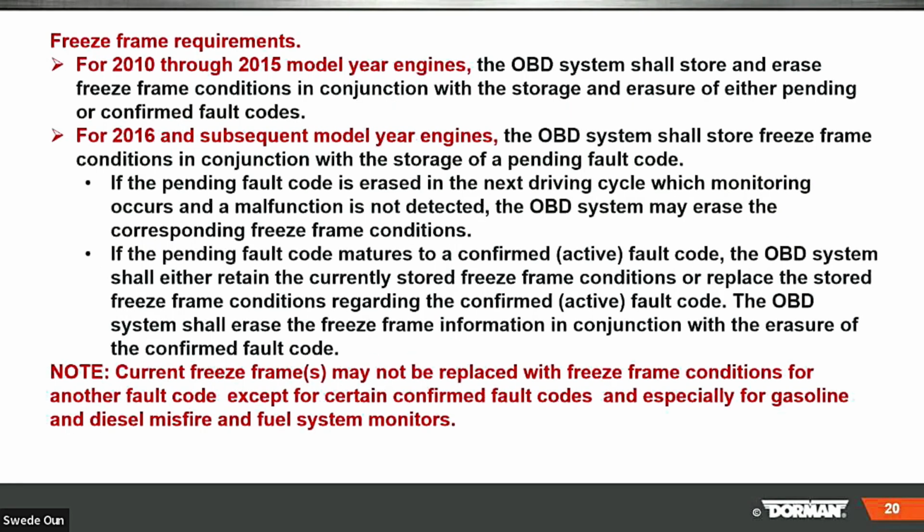So anyway, this is the big one here, the freeze frame. And I know when G does the car portion of the OBD, he emphasizes it. I've done some webinars for him, same thing. All you trainers out there will always mention the freeze frame as part of your diagnostic routine. Trucks are no different. For 2010 to 2015, the OBD system shall store and erase freeze frame conditions in conjunction with storage and erasure of either pending or confirmed codes.